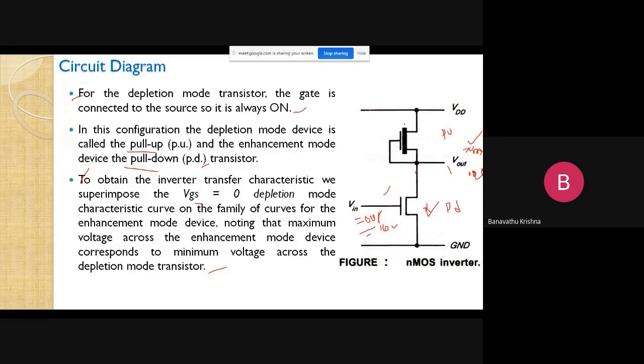Initially, it occupies very high resistance. It is in resistive mode. On condition means it occupies very little resistance, in terms of ohms. The pull down is initially off, meaning its resistance is in terms of mega ohms, whereas from 0 volts, in increasing order,